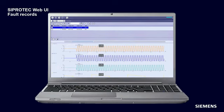Here's an example for a fault record. So keep in mind, this all comes from the protection relay as such, so it's not an extra program. I can show fault records. I can get them first, then I can show them. I can even trigger fault records, so that there is nothing, then I make a trigger and then I have a look, okay, what is going on there. And of course, I can store these fault records on the PC.